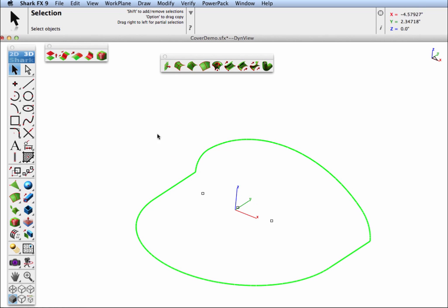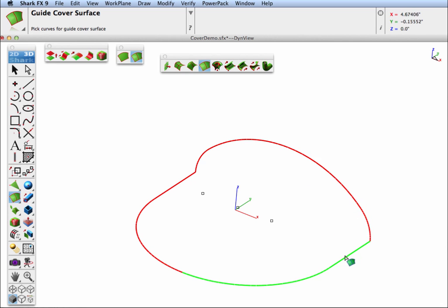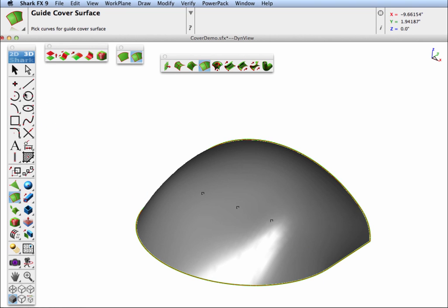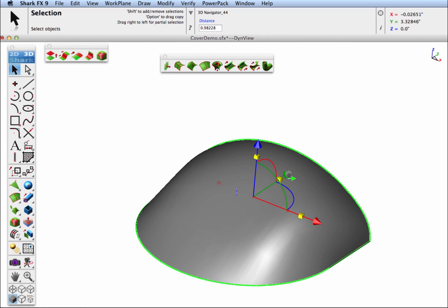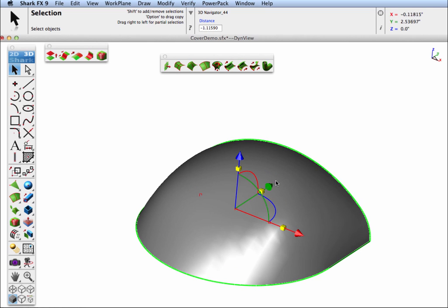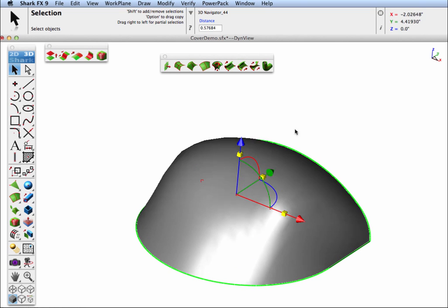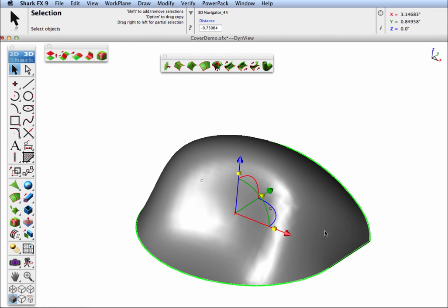And our last example for guide curves is using point entities. Let's go ahead and select all of our outside curves, and then for the inside we'll select 3 point entities. Each of the points then defines a position that the surface is constructed to go through. We're modifying all 3, but you can also go ahead and just modify one individual point.